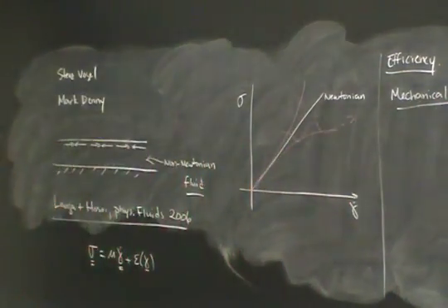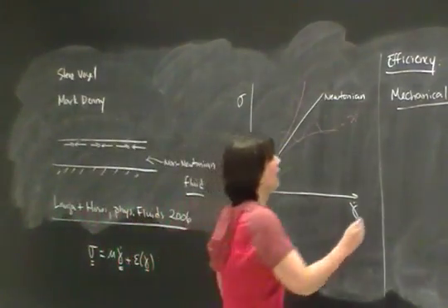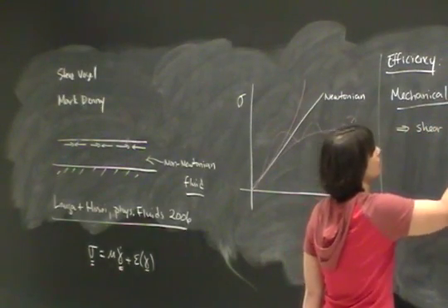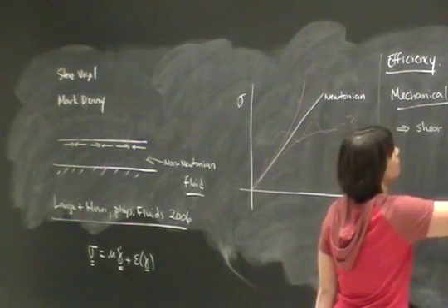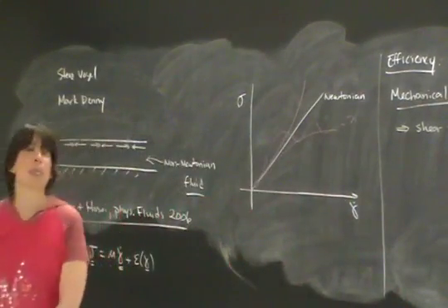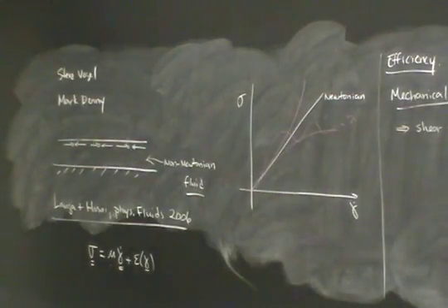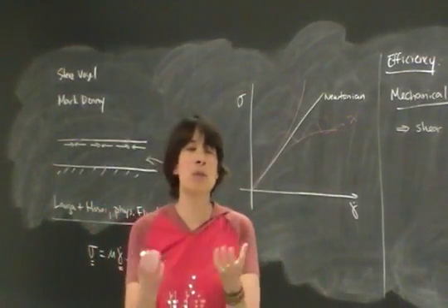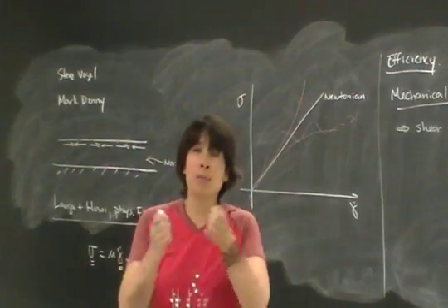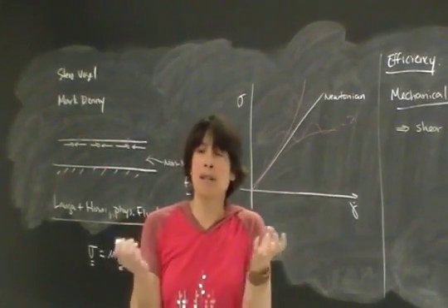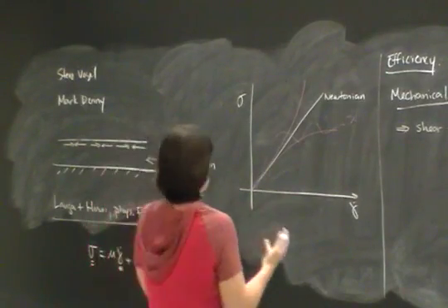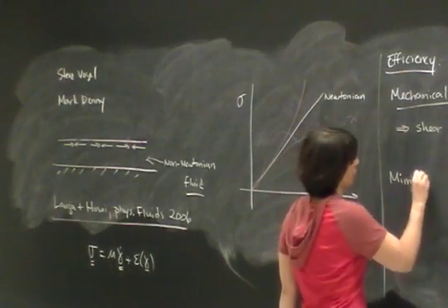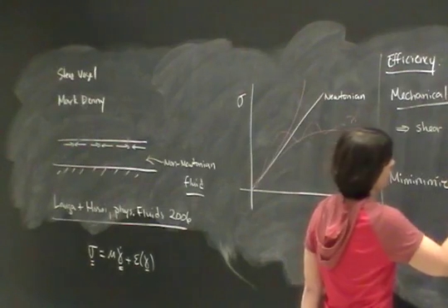Efficiency, you get a nice long expansion, which is written out in this paper, and you find that you are better off if you make your fluid slightly shear thickening. Okay, so that was the first thing you tried. But then the next thing you tried is, well, there's actually another complication in these biological systems, because the snails have to make this mucus as they go along. And the mucus has got all of these big, complicated molecules in them, so it actually costs you a lot of energy to make this stuff. So you may be better off, instead of maximizing mechanical efficiency, to minimize mucus production.